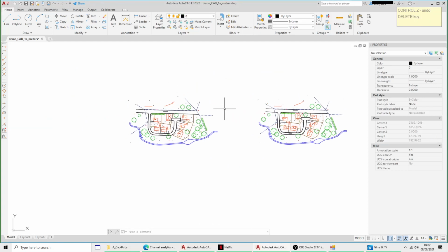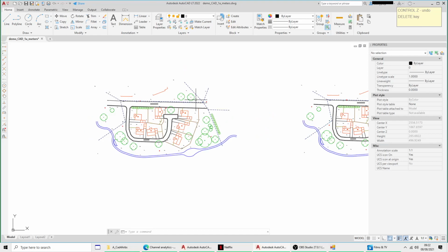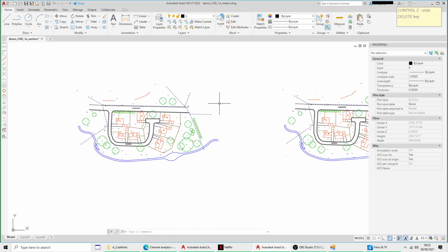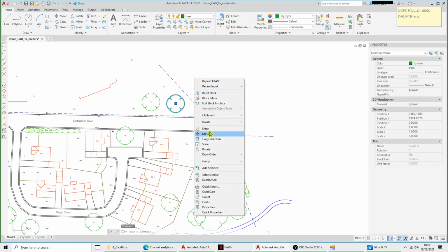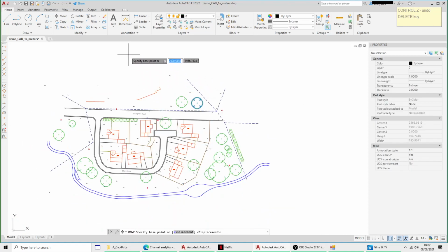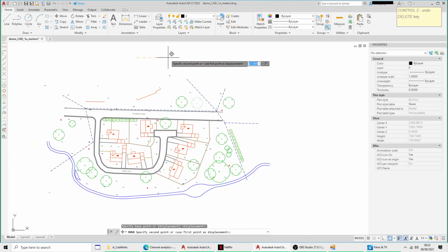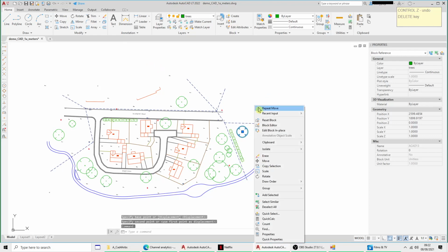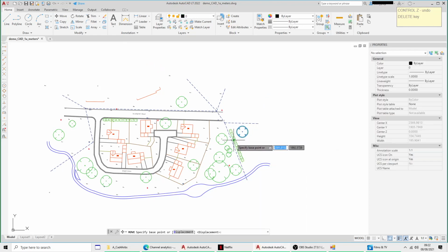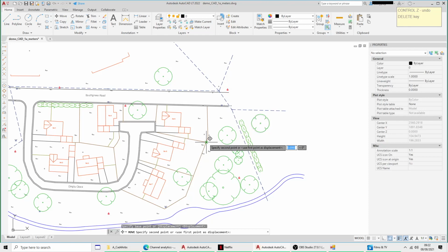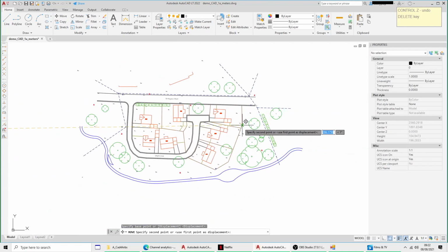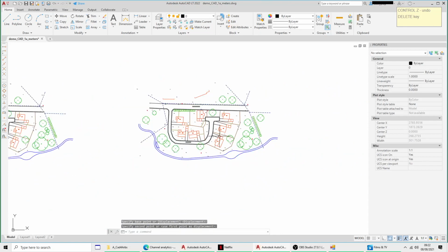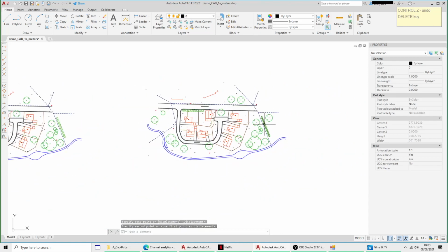So to sum up on those two commands, with move you can either do it sort of freestyle, I call it freestyle. You can just click wherever you like. If you're going to do it by eye, move it to where you want it to go, or you can use base point, where you click something on one, same position on a target, and you've moved it that way.